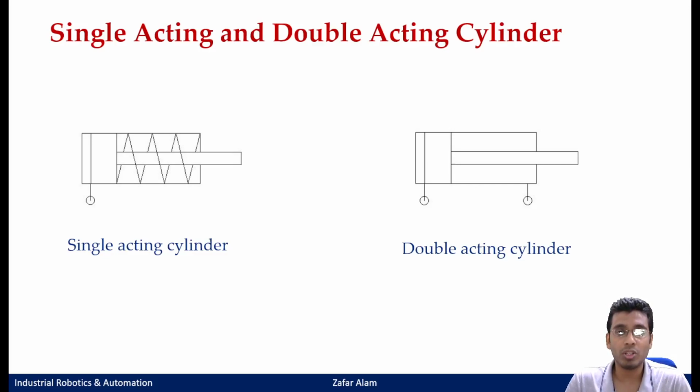Of course, all the components used for a hydraulic cylinder would be able to bear a much higher pressure, because generally the hydraulic cylinder operates at a very high pressure, tentatively upwards of 150 or 200 bars, whereas your pneumatic cylinder operates at a general pressure of around 5 bar to 10 bars. So again all those cylinder walls and linings will be less strong as compared to those of your hydraulic cylinders. But again, the symbolic representation for both would remain the same.